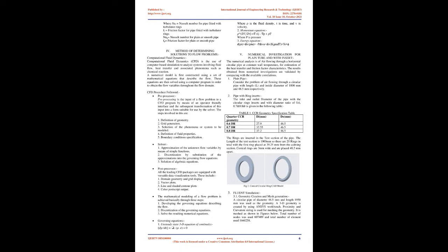Reynolds number is a parameter which indicates the flow regime of the working fluid and is defined as Reynolds number, Re, equals V * D / ν, where ν equals kinematic viscosity of working fluid, m²/s. D equals diameter of pipe, m. V equals flow velocity, m/s.